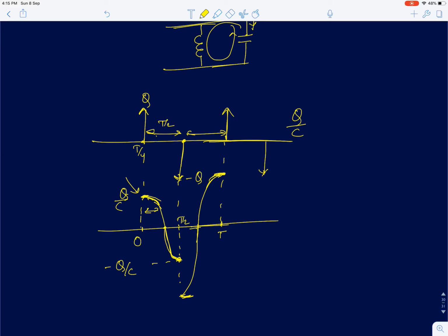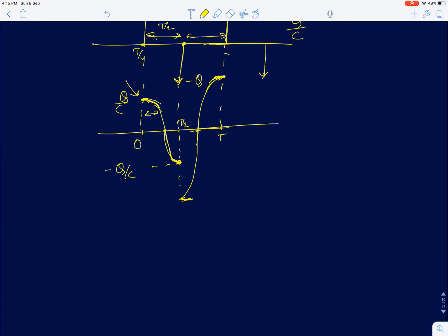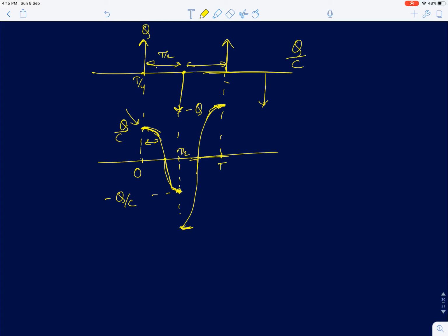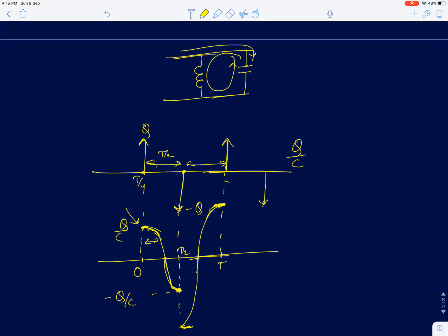Now again at t equal to T, you are injecting a positive charge, so the capacitor is going to store that charge. By injecting impulses every T by 2 seconds, I am increasing the charge delivered to the system. Every half cycle I am adding more and more energy to the system. The energy is always adding constructively. Since I'm adding energy and there is no loss in the system, it's going to store it. So at t equal to infinity, the amplitude would blow up to infinity.